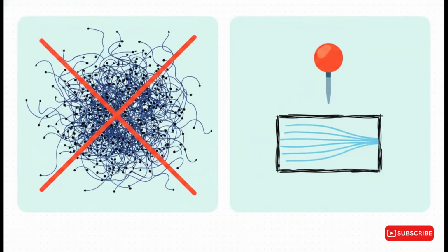But to really understand this, we have to choose how we look at the fluid. Tracking billions of changing individual particles, that's called the Lagrangian way, is literally like trying to follow every single car on a jammed-up highway. It gives you a mathematically impossible system of equations. No thanks. So instead, we use what's called the Eulerian approach. Imagine we just set up a fixed toll booth in space and simply watch how properties like velocity and pressure change as the fluid flows past that one specific spot.